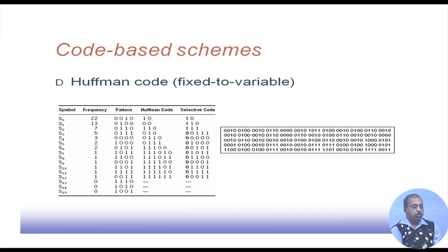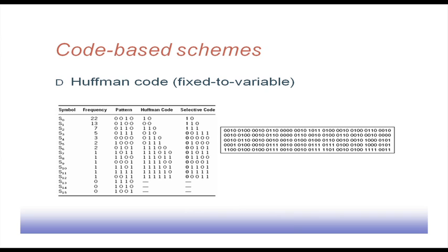In selective Huffman code, it can give rise to further compression compared to the normal Huffman code, and the second advantage is that the dictionary size can be drastically reduced. So, the designer can do a trade off. If you think that you do not want to spend much area for holding the dictionary, then the dictionary size can be reduced, and the dictionary will be able to accommodate only the first few most frequently occurring patterns. The compression will suffer, but that may not be that high, because the most frequently occurring patterns are definitely covered by the coding.